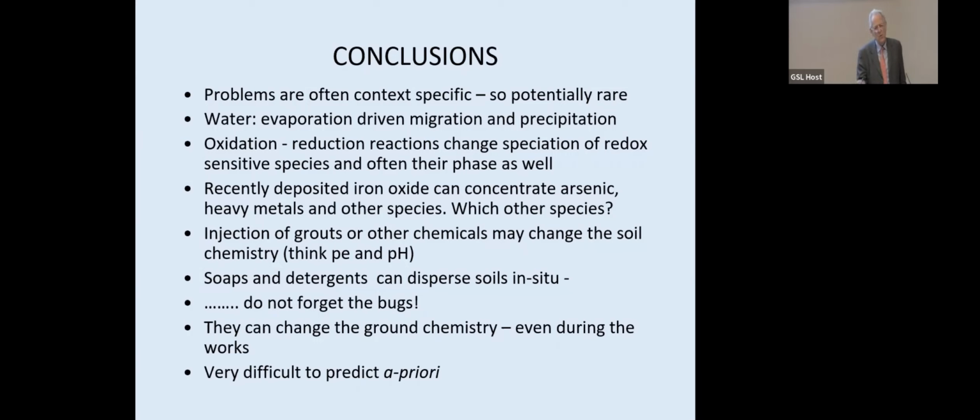And what's the oxygen content of the groundwater? If you're getting precipitation, it's probably slightly oxic, but that's because that pump I showed actually had pinholed through. It was one of the Toby Roberts ones. I'm not sure where it came from. I can't remember now, but it was covered in iron slime and there was a pinhole corrosion pit in it that had caused its failure. So yes, it can happen, certainly. It did happen. Yeah. I have another one.